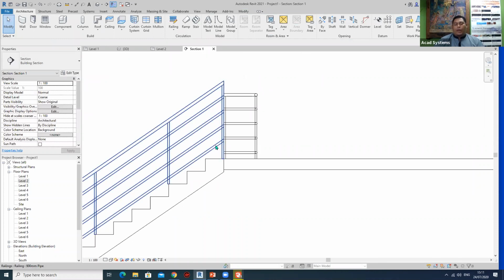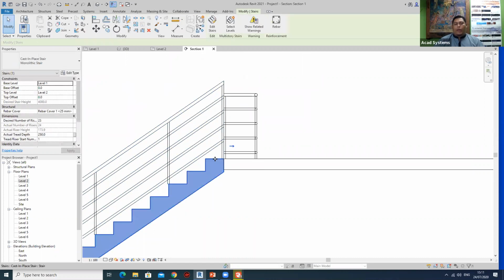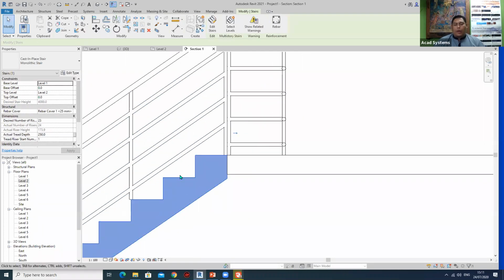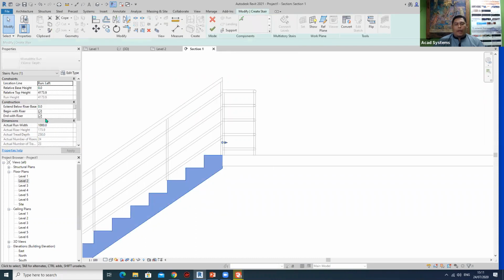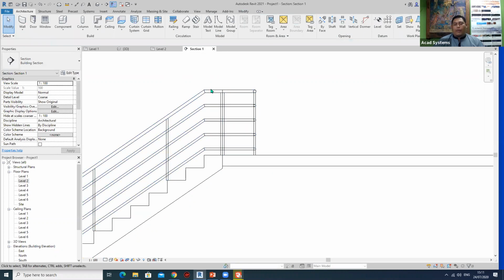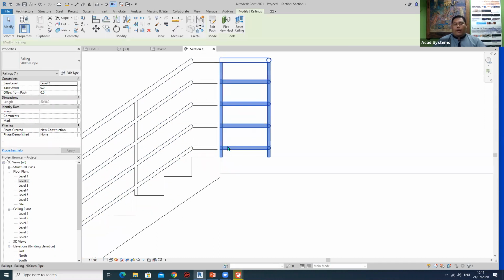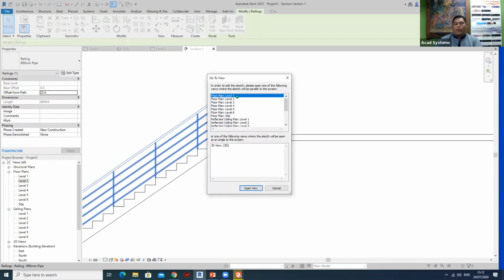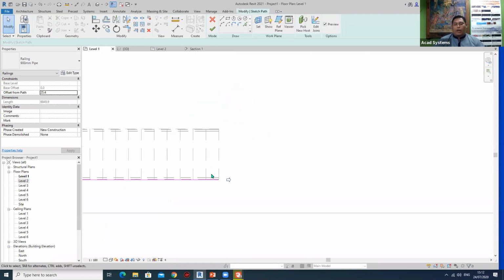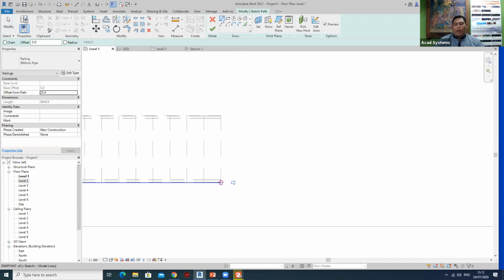In this kind of situation, the solution is to either disable the riser and drag the models up to the floor level, the floor finish level. What I need to do is edit stairs, click at the steps again, untick the end riser, click finish, and you will have a very clear flat railing connected to this. But of course, you will have a different model because I modeled it differently. But if you straight away continue with this, let's say you want to draw straight away.